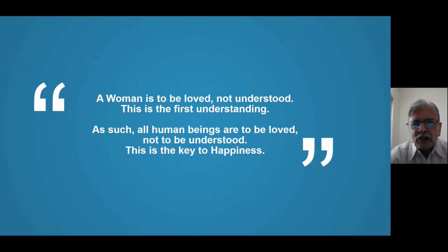So this is a new thing, and therefore I had to talk a little about it. Many viewers might be knowing quite a lot, maybe more than me, I do understand. But there may be many who might not know, so I want them to know. They should throw away the electromagnetic relay. They should throw away the static relay also. And they should use only numerical relays, because the world is of numerical relay.